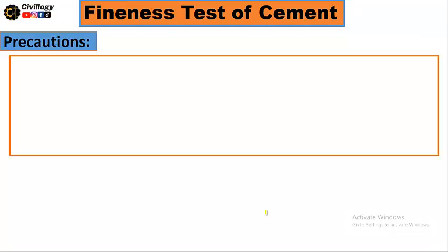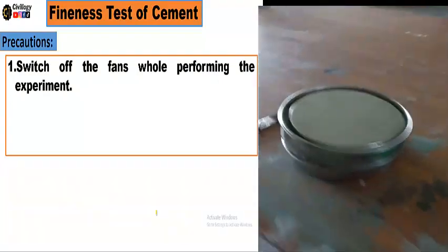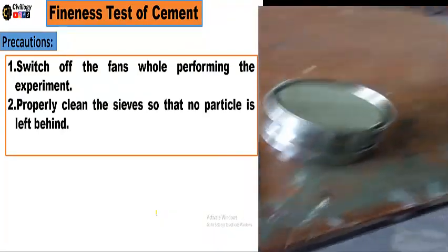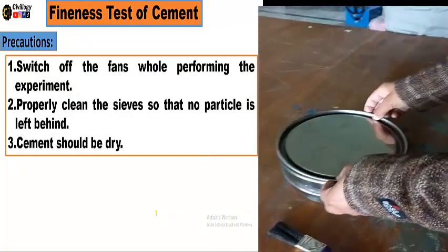And precautions: switch off the fans while performing the experiment, properly clean the sieve so that no particle is left behind, and the cement should be dry.